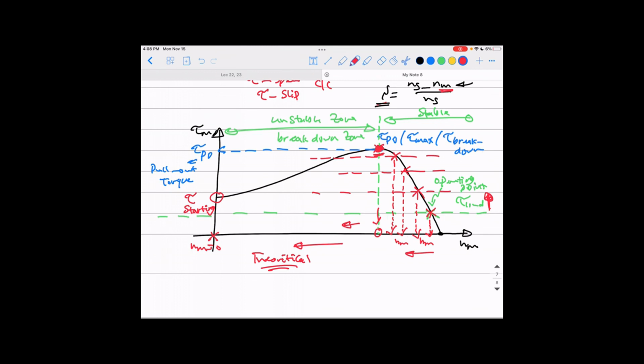Okay, so today we continued talking about the testing of the machine, the no load test, which is finding RC and XM, and used the equivalent circuit parameters we found with our equivalent circuit to derive the torque speed characteristics using the Thevenin equivalent circuit. And now we have our torque speed characteristics drawn here and started investigating it to understand how to use it to see how the machine responds to load change and load variation.